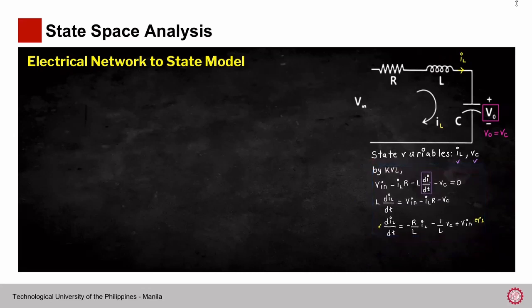So now guys, we know that the current in the capacitor is given as C dV_C over dt, where the derivative here is the derivative of the voltage of the capacitor. Now, since this is a series circuit, this is nothing but I_L, because the current that flows inside the capacitor, since this is series, is also I sub L.